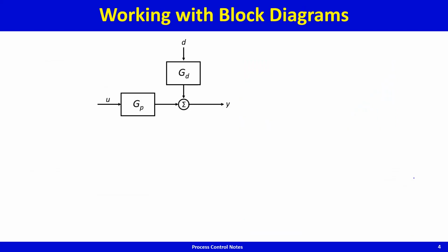Now, because block diagrams reveal the presence of these feedback loops, and feedback loops can cause instability, it is very good to have these block diagrams in front of us so that if there are any feedback loops, it captures our attention immediately, and we do the necessary analysis to ensure that the system is stable. This is particularly relevant for feedback control loops, because there the control is based on feedback of the output that we wish to control. So here is a very simple block diagram,